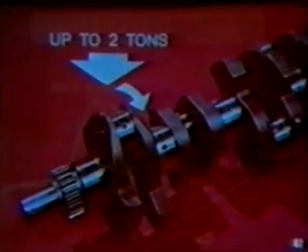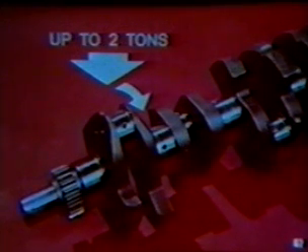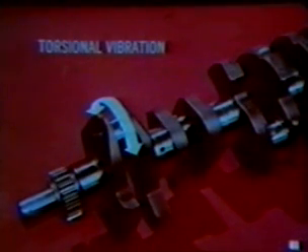As the engine operates, the crankshaft must handle forces of up to 2 tons on the connecting rod journals, which does tend to twist the individual crank pin a slight bit ahead of the rest of the shaft while power is being applied. Of course, the force is relieved as soon as the power is spent, so that the crank immediately flexes back to its normal position. What happens then is a torsional or twisting vibration going on constantly in the crankshaft that must be controlled.